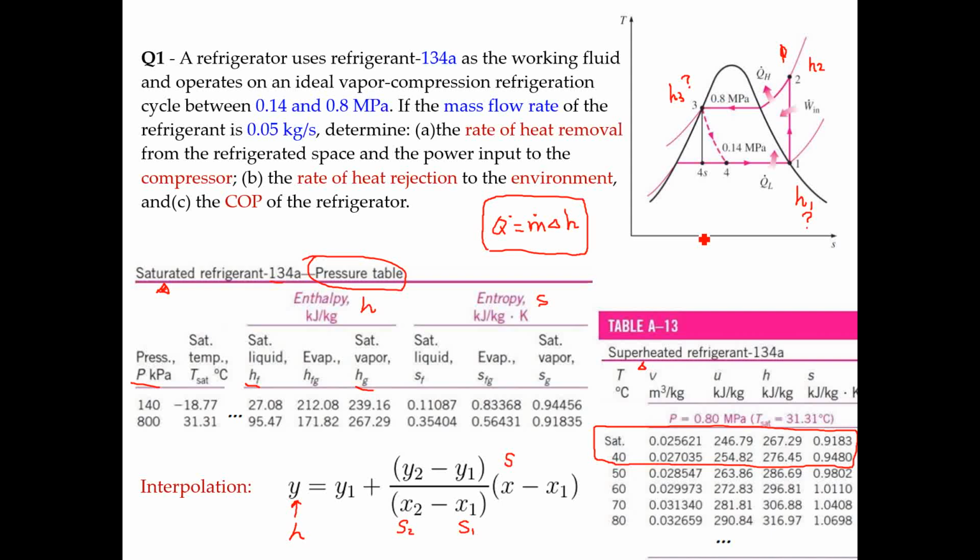Can I ask how these values in the table marry up with the H versus P graph, the enthalpy versus pressure? This should be the same, if they are using the same reference state. So the values in the table would be the same as the values you read from the diagram. Should be the same.